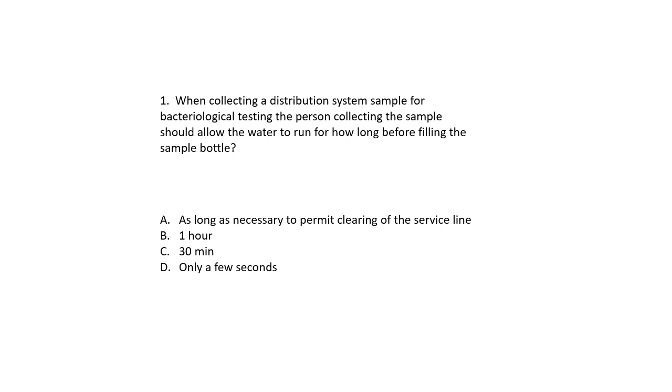When collecting a distribution sample for bacteriological testing, the person collecting the sample should allow the water to run for how long before filling the sample bottle? As long as necessary to permit clearing of the service line, 1 hour, 30 minutes, only a few seconds. Answer is going to be A, as long as necessary to permit clearing of the service line. The majority of failures on bacteriological samples are generally operator error.